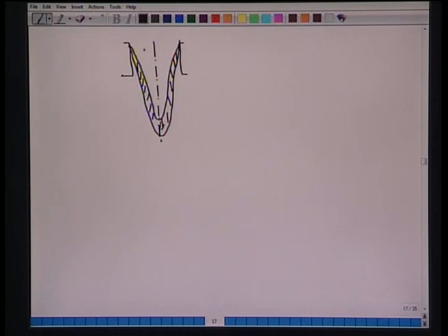So here is all liquid, this is the mold, this is the solid shell which is growing in its thickness as we move downward from the mold, and here all solid. So where can we provide the electromagnetic stirring? We can provide one over here.